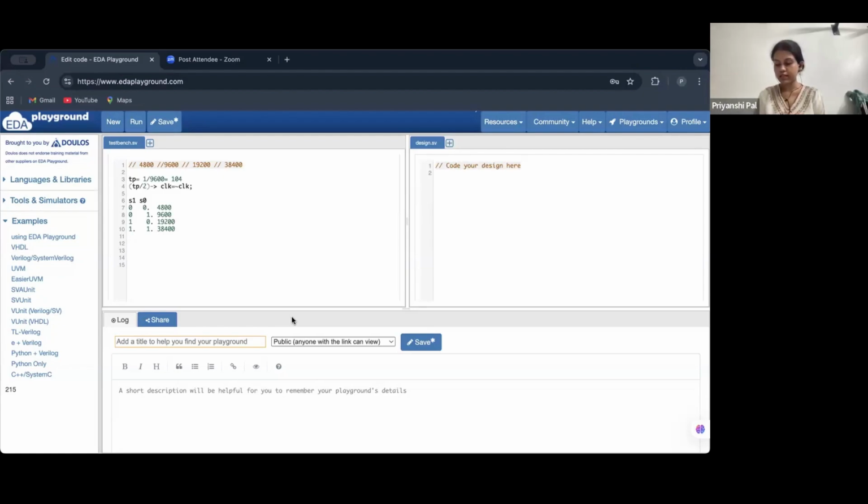Basically, I designed a master, which can be any processor or CPU, and two slaves, which were a temperature sensor and an LED display. The master first sends the slave address and register address to the temperature sensor. The temperature sensor sends the data, for example 55 degrees Celsius, to the master.